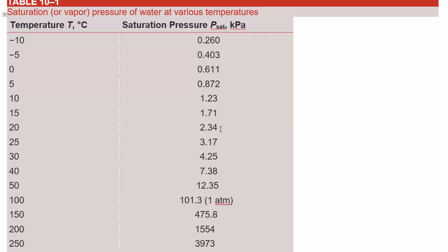All right, so basically what we figured out here is that if you have some water vapor and it finds itself at a pressure which is above the saturation pressure, so if there's too much of it, like when the temperature gets lower, then it condenses. More of it transforms into liquid if the partial pressure of water is too high.